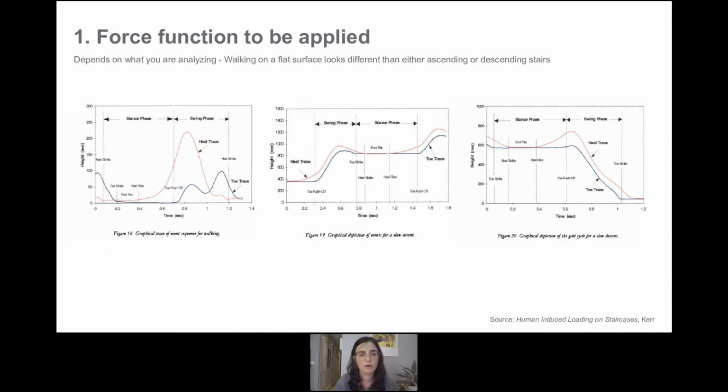So for the case of a stair, a walking forcing function on a flat surface looks different than ascending or descending a set of stairs. So you need to consider all those different components when you're looking at the vibrational performance of a stair.